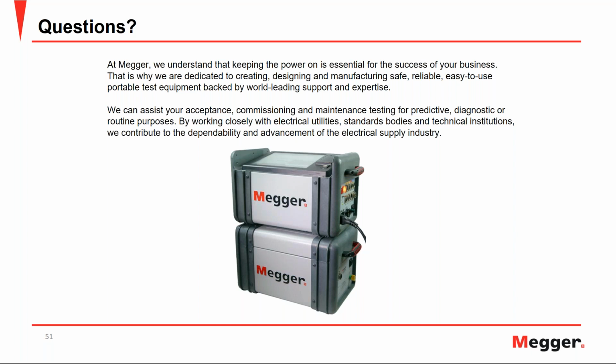All right, thank you, Daniel. My next question I'm going to be sending over to Charles. Charles, for testing a delta-Y 115 kV over 13.8 kV unit, should the voltage applied to the low voltage winding be limited to 13.8 over square root 3?